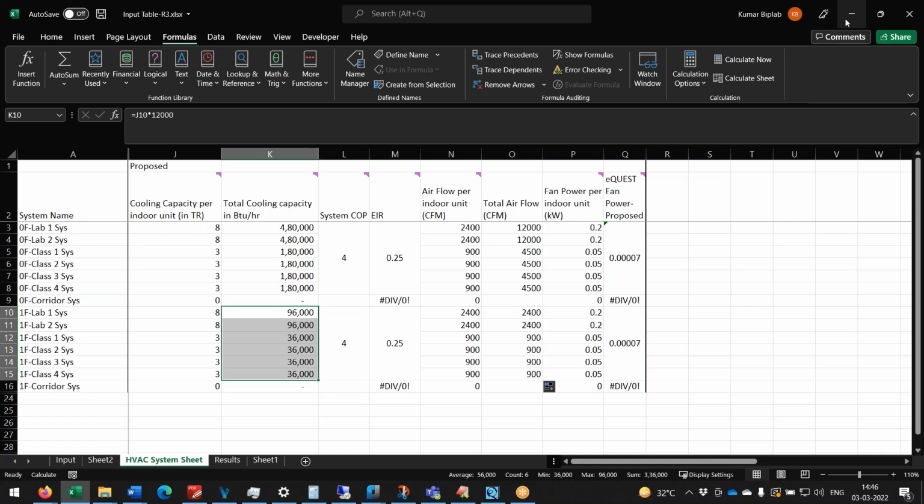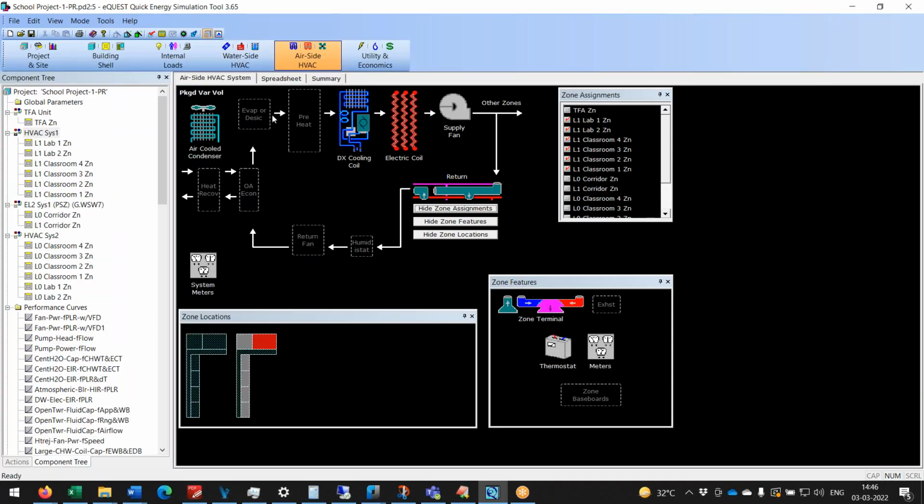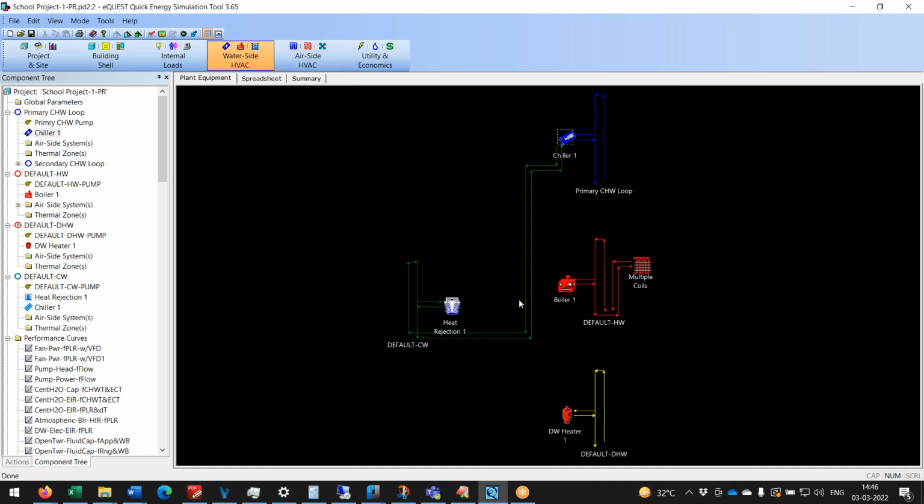Right, and that is number one. When we come to a chilled water based system, obviously the cooling tower, or the heat rejection size, is higher. One of the main reasons is that water is the transfer medium over here, and the delta T that you achieve is significantly less than on the evaporator side. So that is why in the case of chilled water, the tonnage is higher.